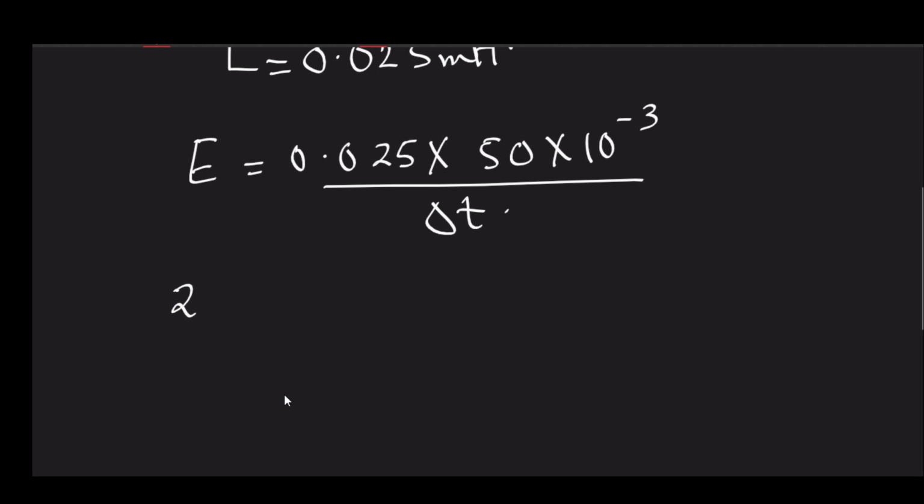So you need dynamically induced EMF in the commutating coil. That is how much it will be. The magnitude will be 2 BAV. This is for a single turn coil. If for multi-turn, you have to consider it N. For single turn, it is two sides, that is why 2. So here, if this armature conductor moves a linear distance delta x in delta t second, then we can define V like delta x by delta t, right?